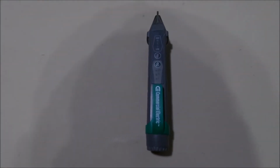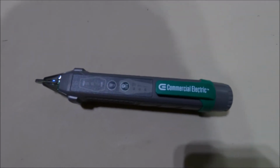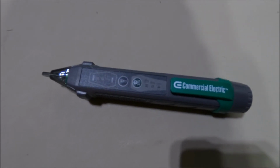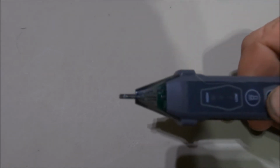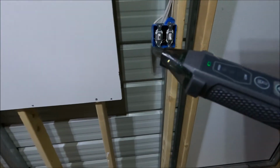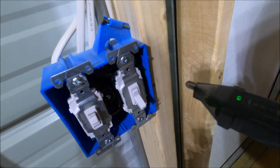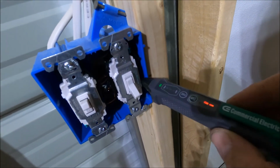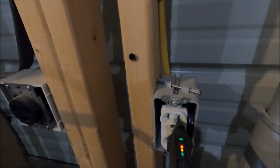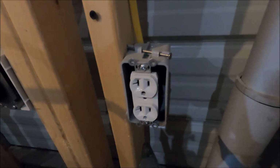The next tool I'd recommend getting is a non-contact voltage tester. A lot of the professionals call these death sticks. I don't think they're that dangerous if you know how to use them properly. What you'll do is turn them on, and wherever you come in contact with voltage, it'll light up and tell you that somewhere along there is voltage. So obviously if this lights up, there's a live circuit in some capacity.